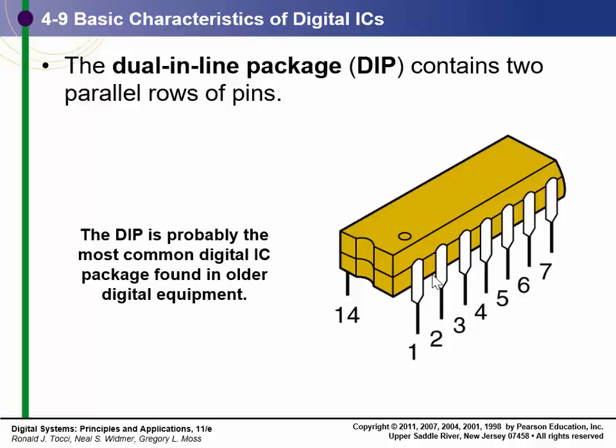And later on, we'll look at what they call surface mount. Surface mount means that you basically place a part on top and it's soldered to the top of the board, and the connections are done through the top and bottom and the intermediate layers of the board. This is not a course on board layout or electronic fabrication, but an older type, when I first started, a dual layer board was considered complex.